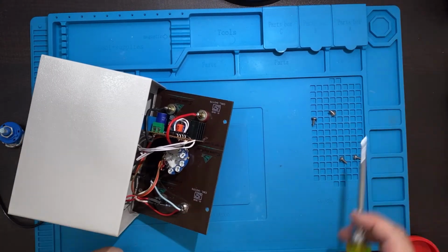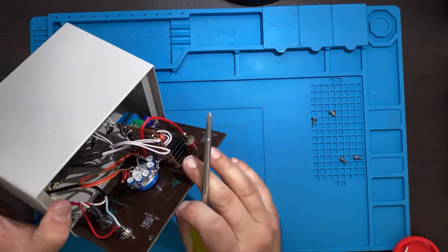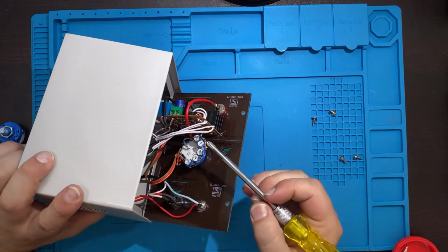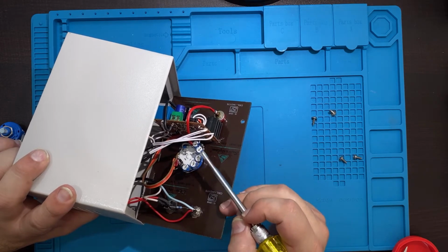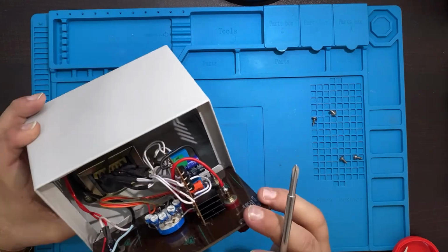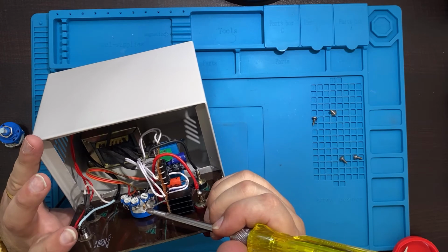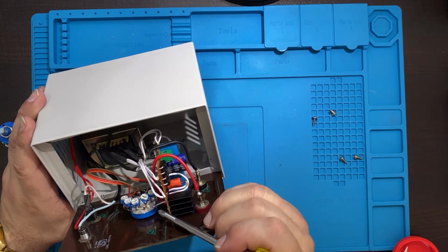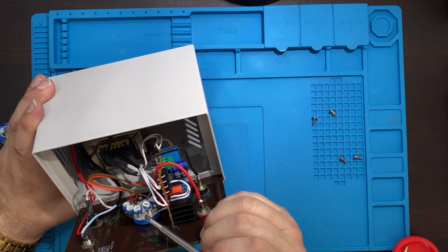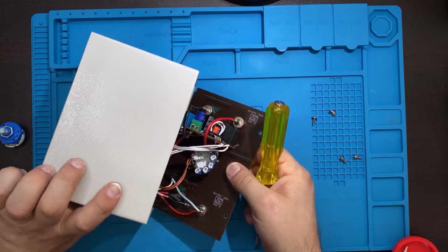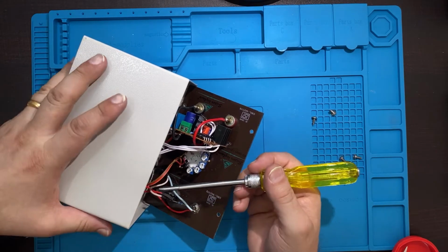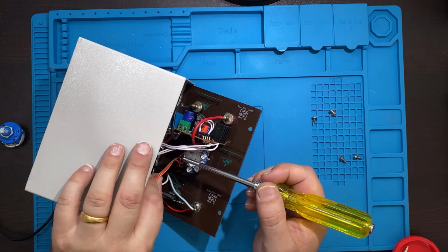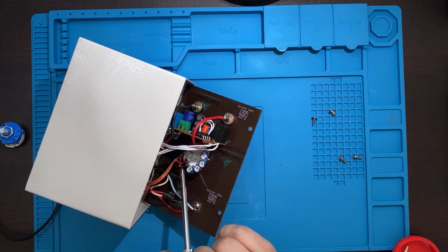So instead of having to select the closest resistor to get a close voltage here, I used trim pots, 10K trim pots, and for the highest voltages, there are series resistors with the trim pot, 1K and 27K, 27K for the 18 volts, 1K for the 13.8. And here on the other circuit, here are the 3 selection wires to select the relay, 2 diodes to select both.